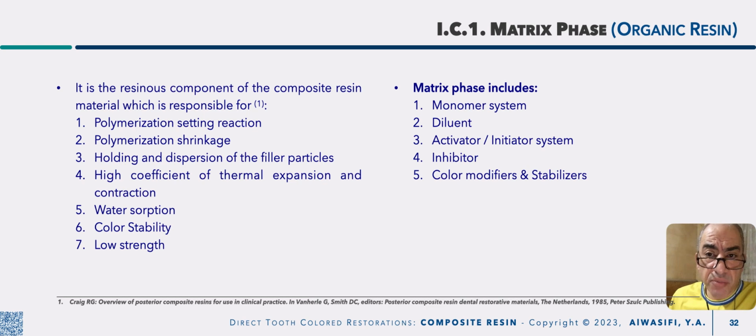Considering the matrix phase, it is the resin component. It is responsible for the setting reaction. This is the part which undergoes reaction and produces setting and lets the material harden. That is why it is the part responsible for the amount of polymerization shrinkage. When it shrinks or hardens, it grabs your filler particles.